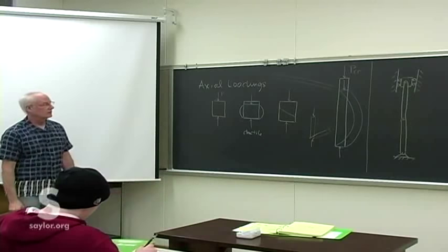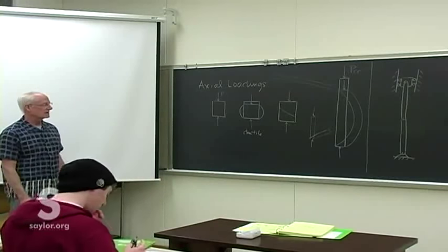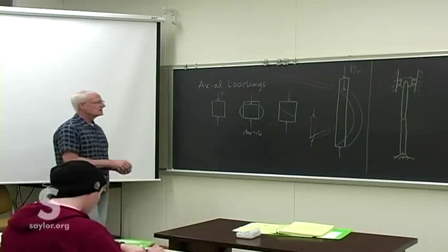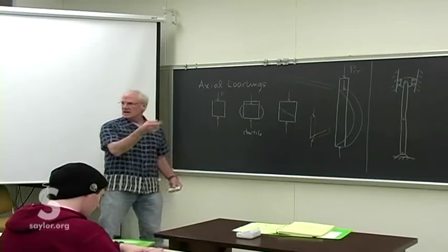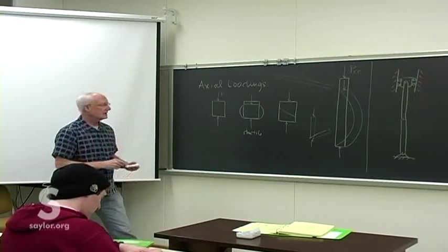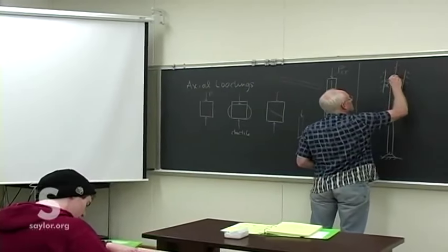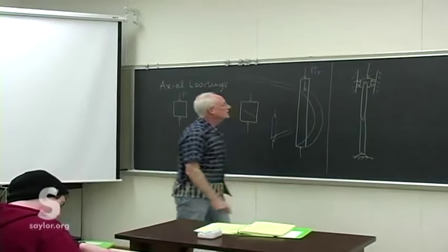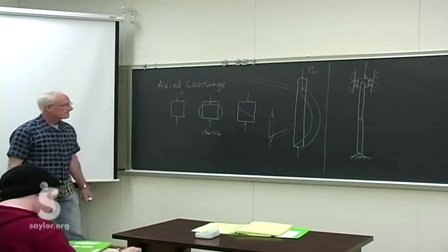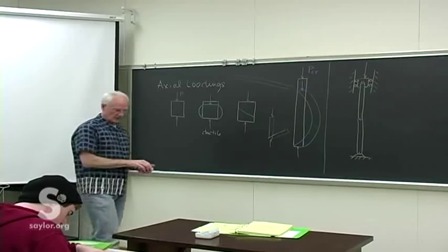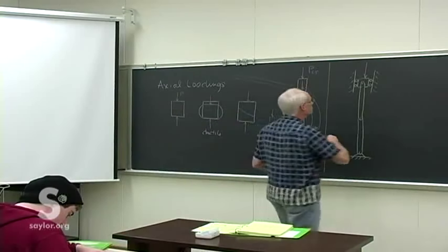We don't even have any real loading on the piece, we just pushed it aside. So we've got to keep it so that it's stable side to side, but free to move up and down. And then we'll apply some load to that and try to see what we can estimate for its possible failure.